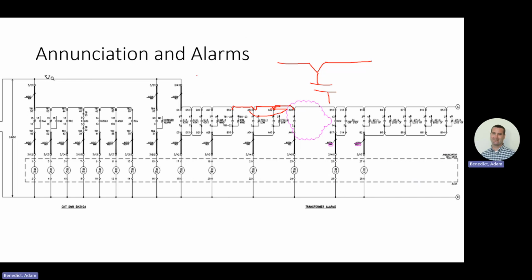Typically, if the schematic is just more like this, then it doesn't matter how you wire it. But if it's up and down, if it goes in and out, that's usually an as-wired type schematic, versus this, which is just a node, right? So you could wire this however you want. You go 3C1 to 3K1 to 3D, whatever makes sense to you. But this indicates to me that I should wire it D4 to D12 to D20 to A27 to B52. But that's not always the case, and if I saw the schematic, I would definitely ask the question.